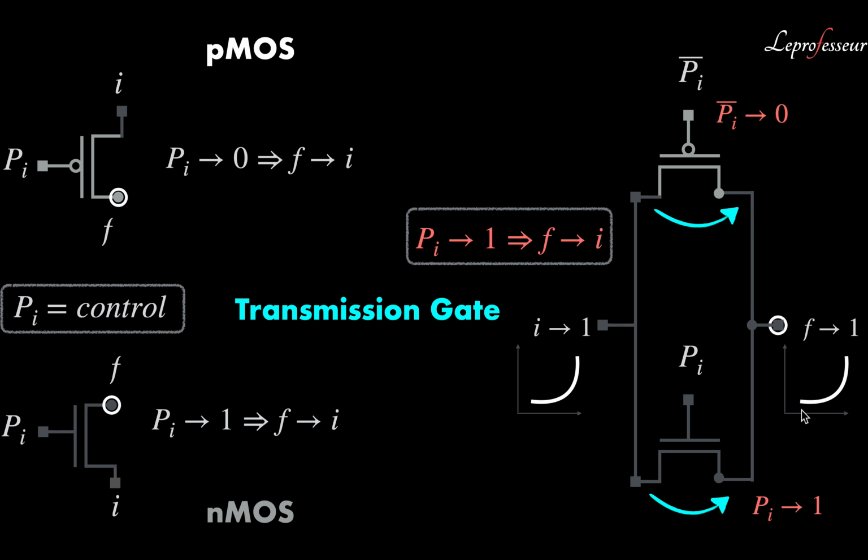In other words, the purpose of this gate is to transmit a logic level from the input to output and maintain the logic level at the output node so that no extra circuit is required. So we established what a transmission gate is. We call it rail-to-rail swing of the voltage. A very important fact.